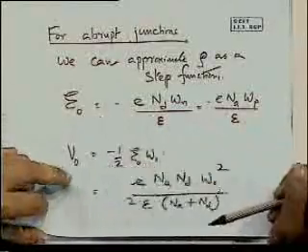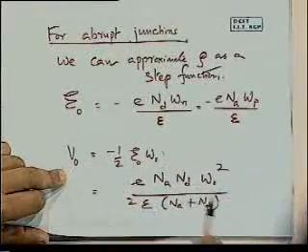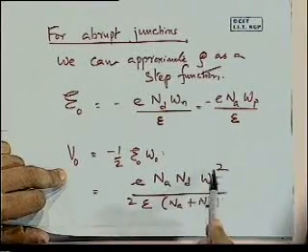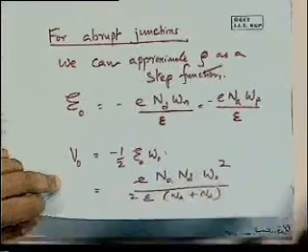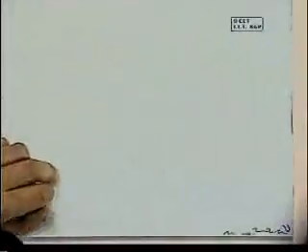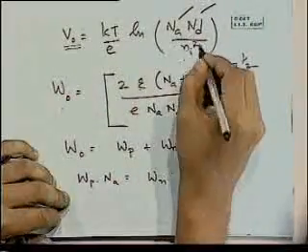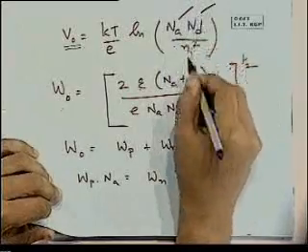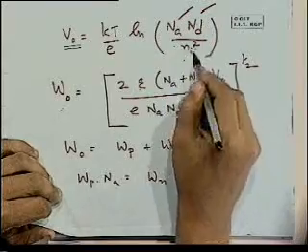And from that we calculated that the potential V0 is given by an expression that involves acceptor concentration, donor concentration, and the depletion layer width, which we didn't know here. So we obtained another expression that relates the built-in potential purely in terms of the acceptor concentration, donor concentration, and the intrinsic carrier concentration.